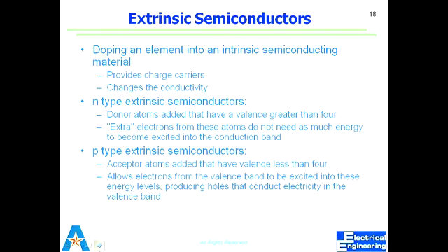Generally we dope them with two types of materials. One is N-type and one is P-type. N-type contributes electrons, P-type contributes holes. Knowing the actual physics, there's nothing like holes, it's just the vacancy of charge, what we call holes, but we treat it as a charge carrier. So when we speak of current flow, we speak of hole flow, or electron flow, charge flow. You will seldom hear me saying current flow. Charge travels. The hole we treat as a positive charge carrier.